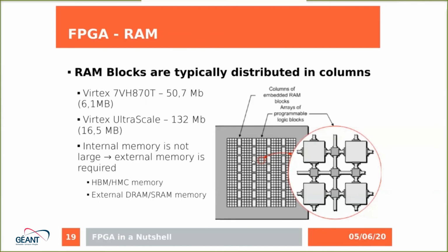The structure or the properties of the RAM memory typically depend on the FPGA, but we can say that very typically the memory has two independent inputs. So you can work concurrently with the memory block from two sides. You have two independent address inputs, two independent data inputs, data outputs, and so on.